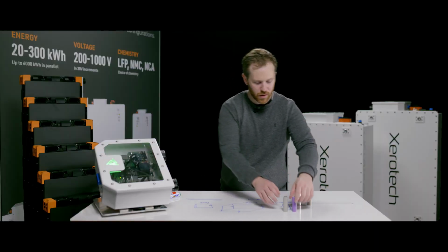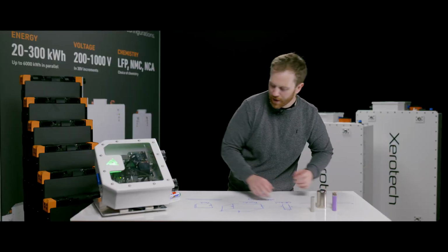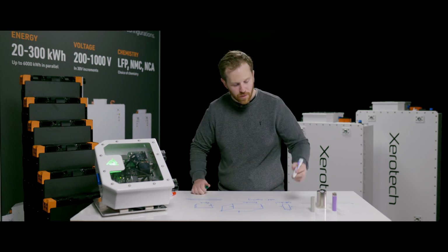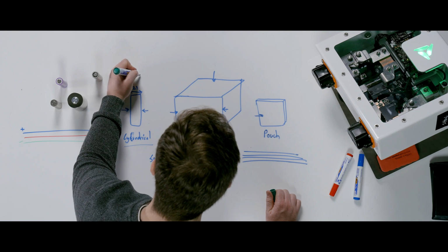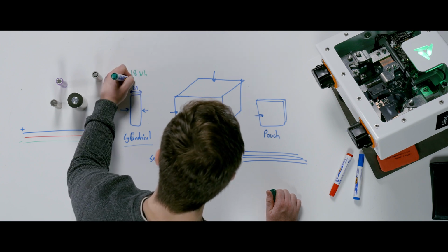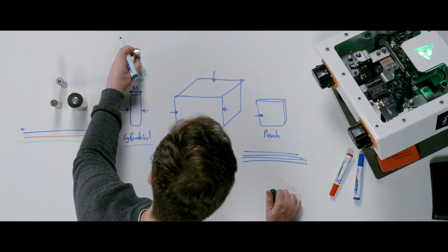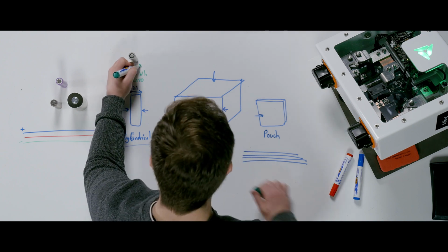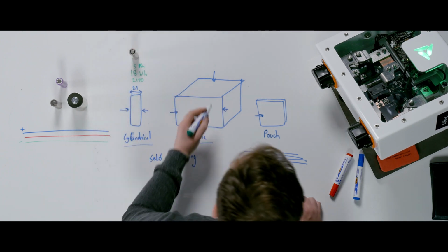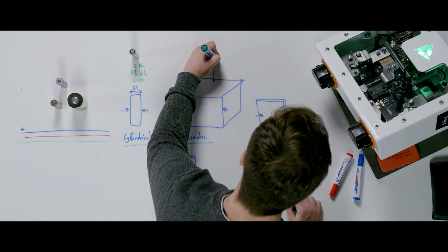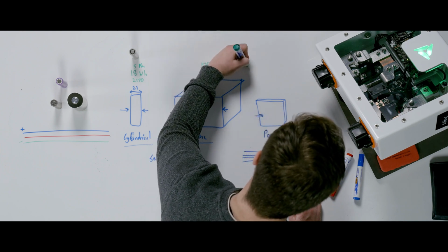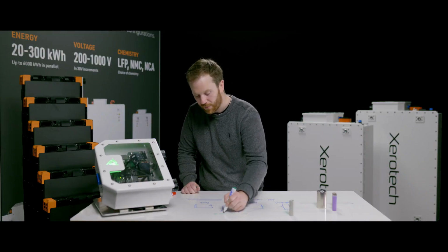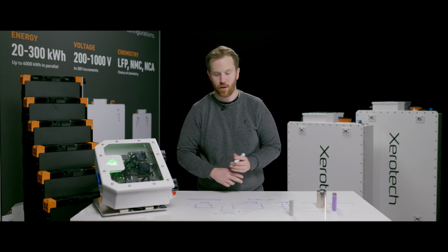And that's something that I want to consider in terms of the fundamental choice of us building our own battery packs here at Xerotech with cylindrical cells. The amount of energy in a cylindrical cell can be about 18 watt hours for a 2170 battery cell, a cell like this. For a large prismatic, because this is 5 amp hours for the cylindrical cell, prismatics can be 100, 200, 300 amp hours. That means that they can have energies in the kilowatt hours range of energy, much more energy.